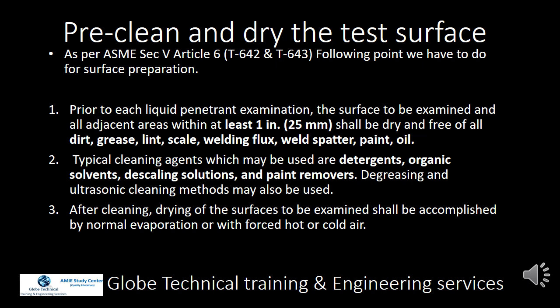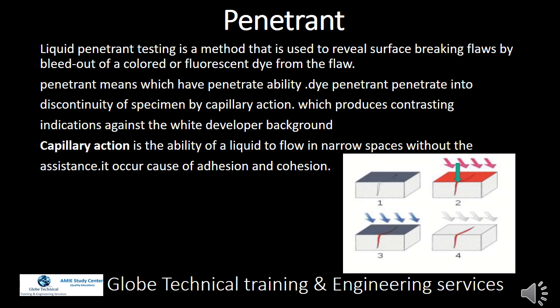After cleaning, drying of the surfaces to be examined shall be accomplished by normal evaporation or with forced hot or cold air. Penetrant. Liquid penetrant testing is a method that is used to reveal surface breaking flaws by bleed out of a colored or fluorescent dye from the flaw.